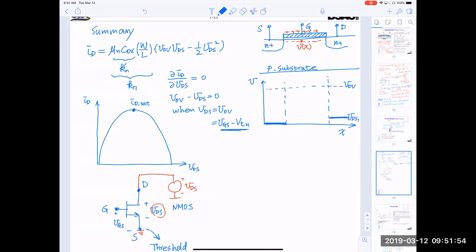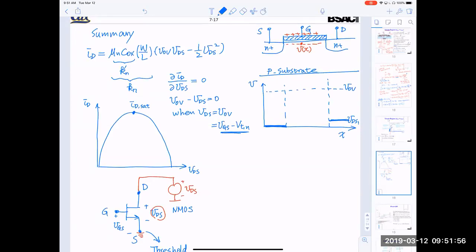So it's a straight line across X here. And our lengthy mathematical derivation last time basically says the channel potential varies in between source and drain. We did not assume it to be linearly varying, but at low voltage, it's pretty close to linear. You don't need to assume the specific relationship because we simply integrate over the entire area.